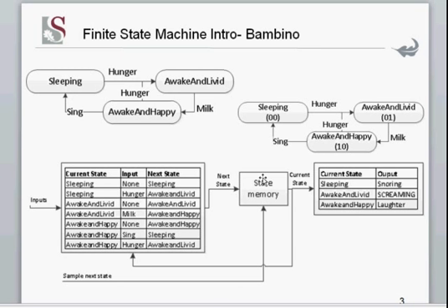Just as you as a human remember what state you're in. If you're in a state of tiredness or in a state of being awake, you have that built into your system. In order to emulate that using electronics, we use memory. And the only memory device that we really know that we can use is a flip-flop. And that brings me to the second last point, which is that we need to sample this at a certain time. And this, you should realize, is the clock that drives the flip-flops.